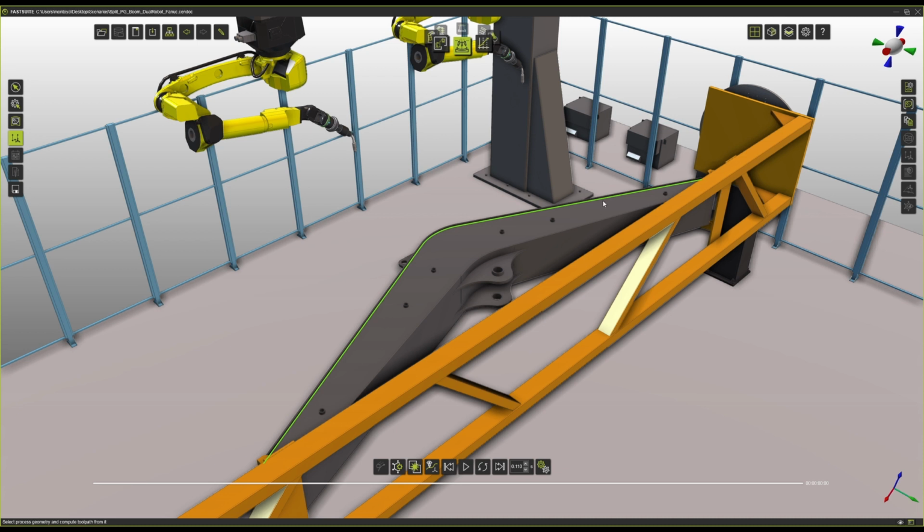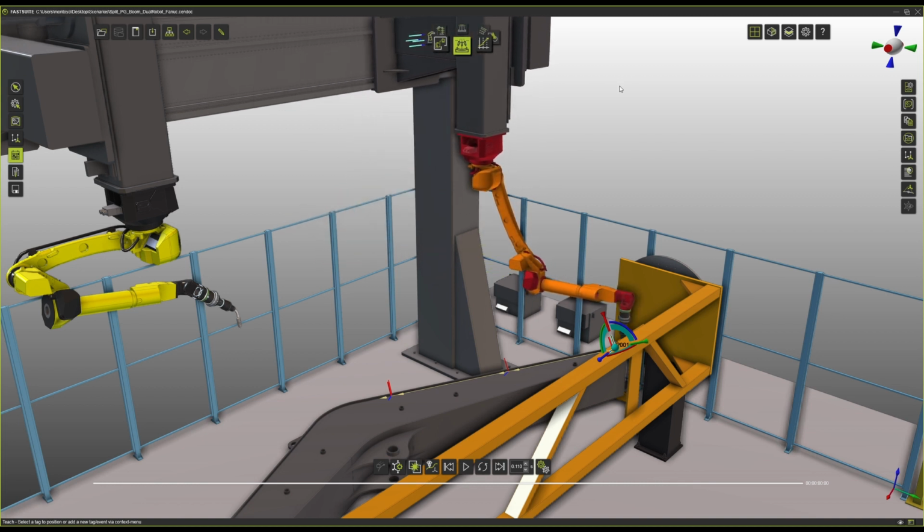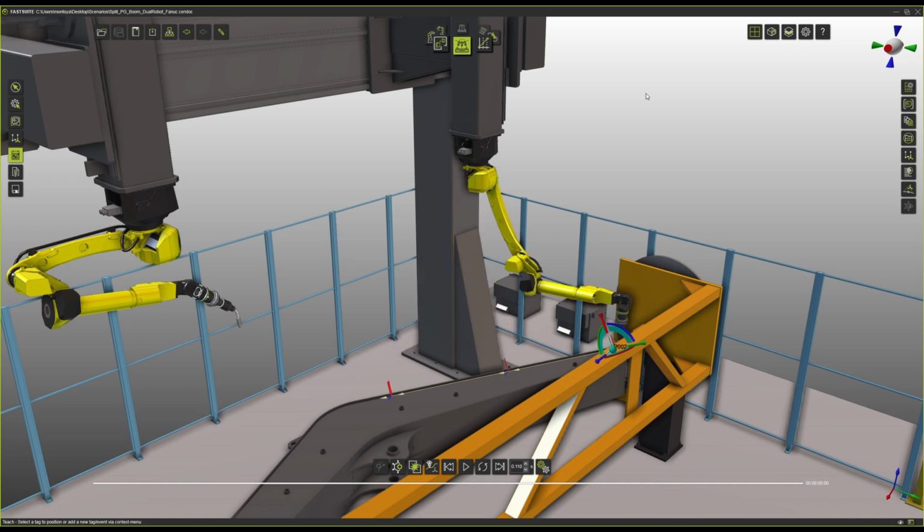With robot number 2 selected, I'm going to click on the process geometry and shorten the part that I want to be programmed. Then I'm just going to confirm and I'm going to have a shorter path. In order to reach the first point, I have to modify the external axis of the robot. Once we confirm, we can verify that we can reach the entire path.